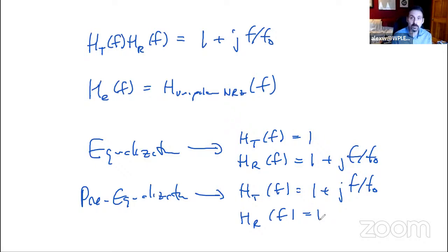Equalization, it's great. Essentially at the receiver, if I know what the channel conditions are, I can tune F naught, because let's say F naught changes. Let's say the resistance and the capacitance change over time. That's a problem. But the problem is if I have noise, we didn't talk about that, I also apply my filtering to the noise. There are reasons why I don't want to touch the noise at the receiving end, because there's potential for me to amplify the noise. Everything that comes in is whatever signal plus noise, so ideally, I don't want to touch the noise.